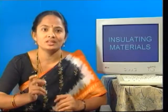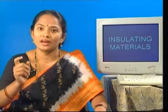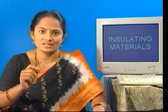The mechanical properties such as impact strength, tensile strength, toughness, hardness, elongation, flexibility, abrasion resistance, etc. have to be considered when choosing an insulating material. Also, the machinability and resistance to splitting are equally important. In case of varnished products, the bonding property of varnish is important.